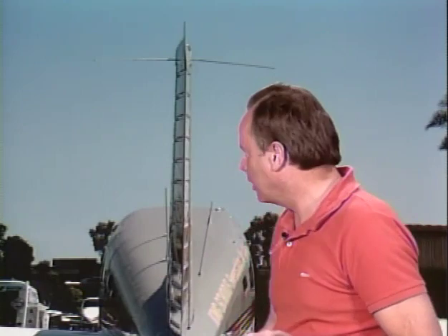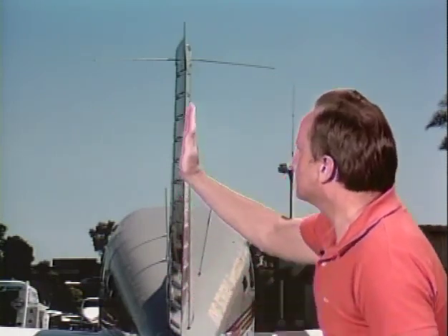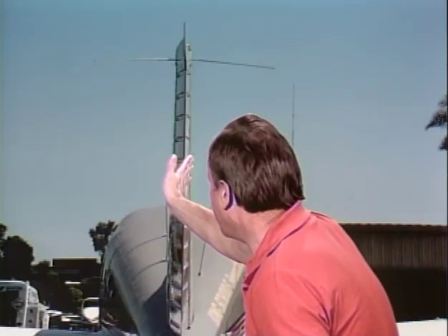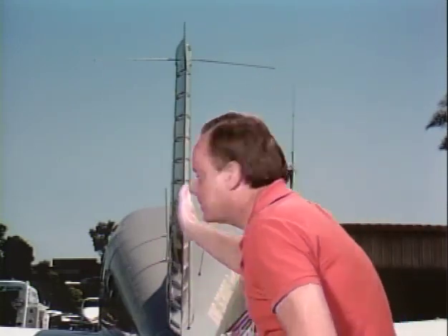And if the vertical tail of a single-engine, propeller-driven airplane is rigged properly, it will generally be, according to the FAA, parallel to the vertical axis. In other words, it'll be right straight up. But it will not be parallel to the longitudinal axis because you need to have a little bit of an angle there so you can correct for the natural left turning tendency of the aircraft. So if a vertical fin of a single engine propeller driven airplane is rigged properly, it will generally be parallel to the vertical axis but not to the longitudinal axis of the airplane.